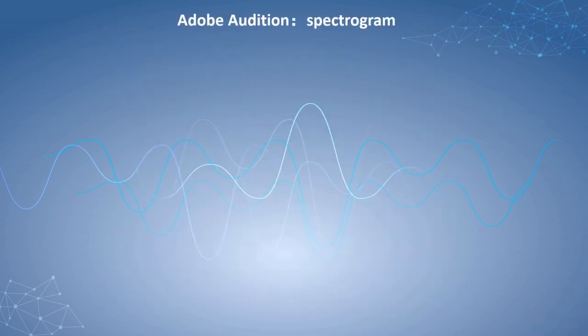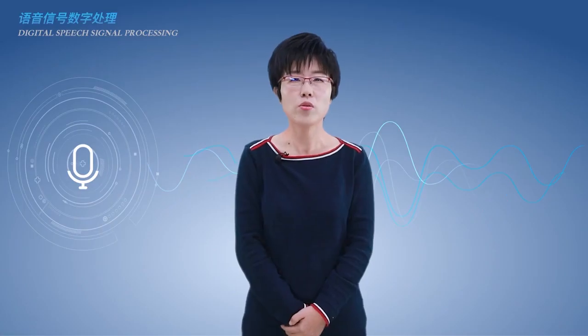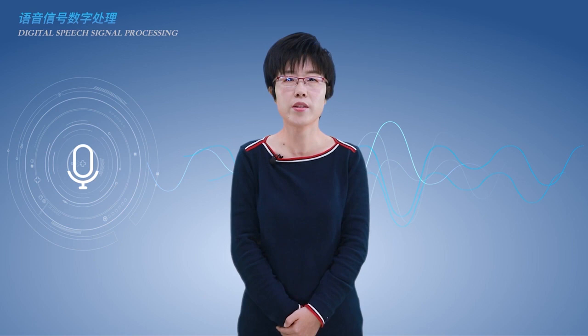The function of the spectrogram will display a colorful two-dimensional time-frequency image in which the deeper color means higher energy. Spectrograms are usually created in one of two ways: approximated as a filter bank that results from a series of bandpass filters, or calculated from the time signal using the Fourier transform.